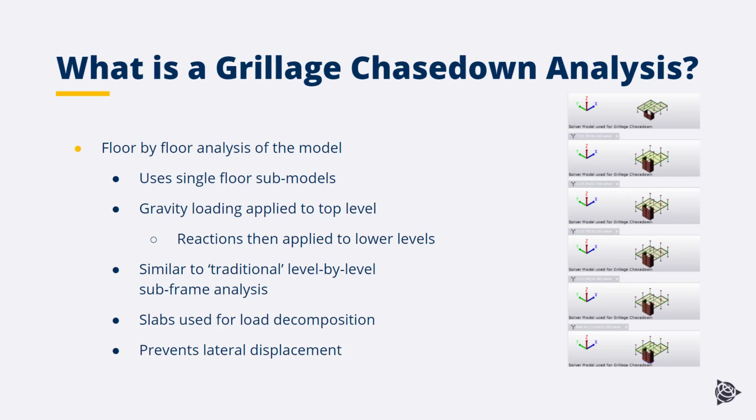This method of analysis would be similar to a level-by-level subframe analysis that would traditionally be done using the tributary area method. In this analysis, the slabs will be used for the decomposition of loading, applying the load directly to the supporting members and wall panels, similar to how it would have been done in the 3D building analysis.